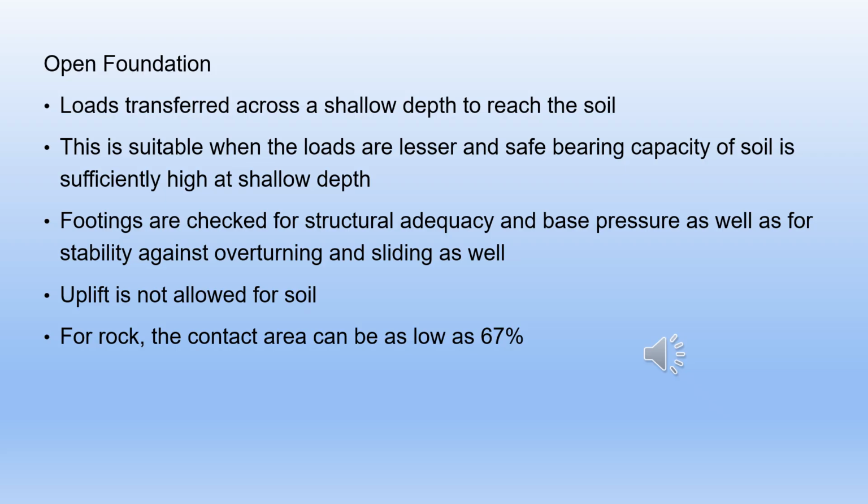Footings are checked for structural adequacy and base pressure as well as for stability against overturning and sliding. Uplift and loss of base contact are not allowed for foundations in soil. For rocks, the contact area can be as low as 67%.